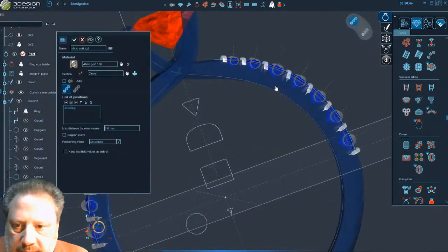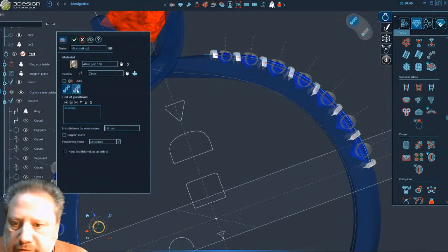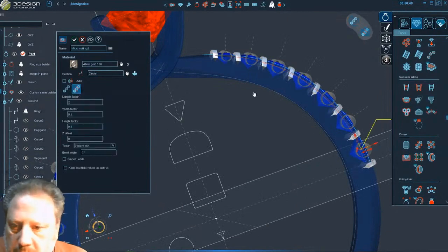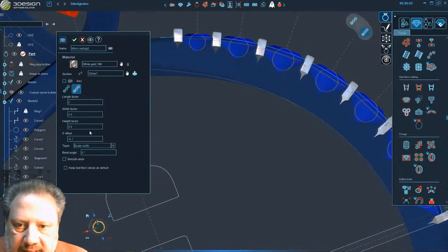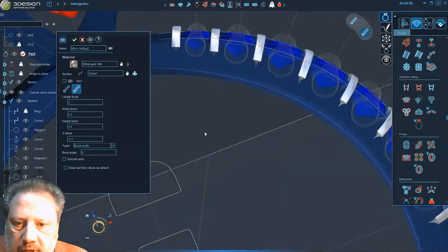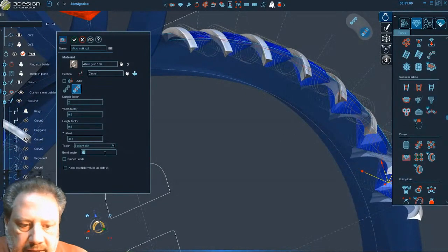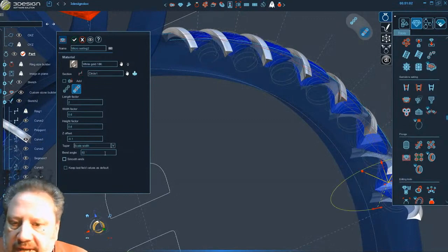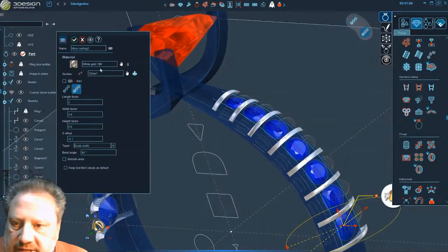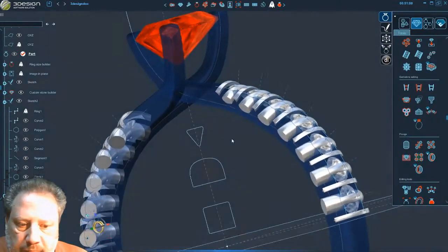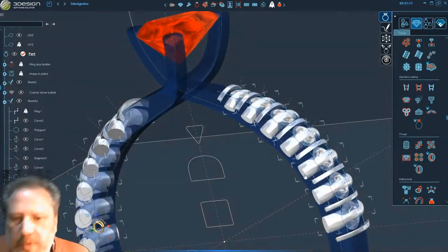Take the circle as a profile, and I will also bend it, maybe resize the height and the size of my circle. Yeah, why not? Looks okay. I have the space, and I will bend also my 80 degrees. Okay, validate. Yep, looks good.